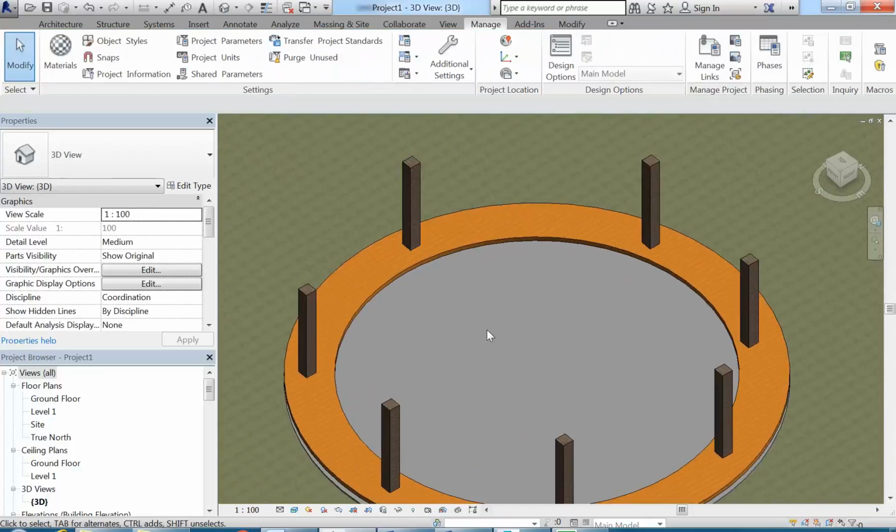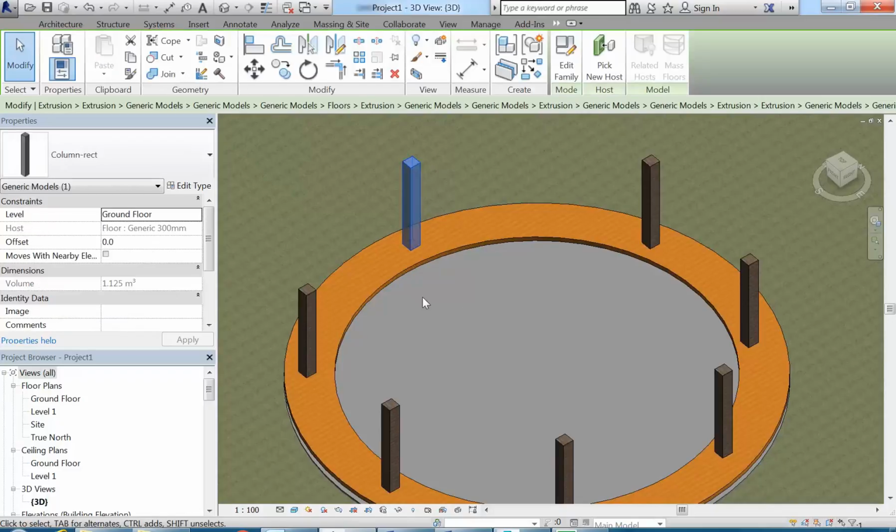And this is really the key to learning Revit. So at first, if you're just using things out of the box, things from the library that have parameters set up for you, you're not really using Revit to its full potential. And to actually know Revit, you need to understand families and how parameters and those other options that make families adjustable interact with families. That's really the key to understanding and knowing Revit. And the simplest one to start with is a material parameter. So I know I've shown you a little bit about parameters before, but I just want to keep going with that. So I'm going to select the